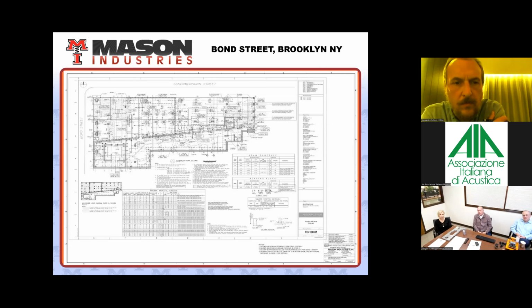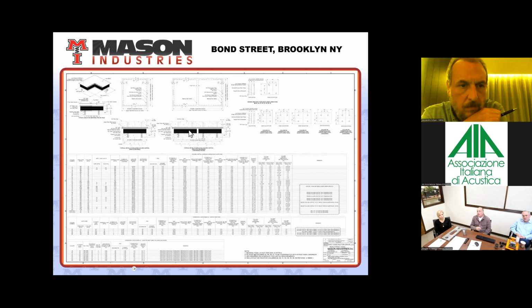So the idea was the building is partially over the subway itself. There's no vertical load, there's no horizontal load that can be transmitted to the subway. So in this particular instance, we had bearings that actually slide, and that's what these bearings show. There's stainless steel interfaces and Teflon sliders on top of the bearings so that the building is free to float on top of the bearings and move as the vibration is generated. So there's no horizontal load that gets transmitted to the structure.